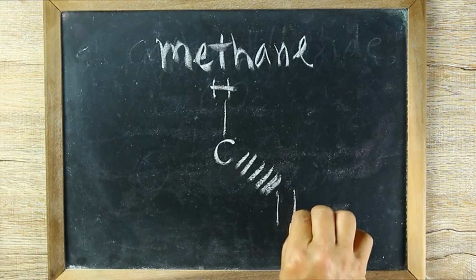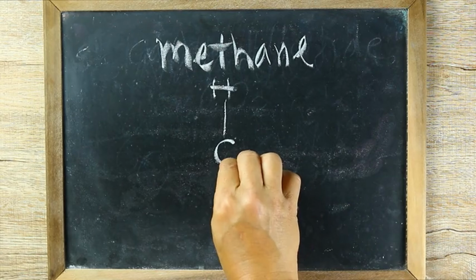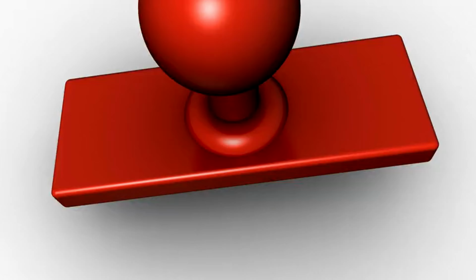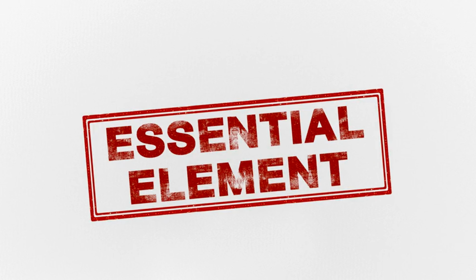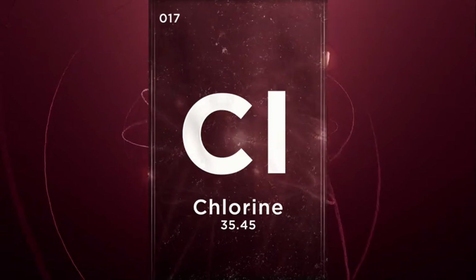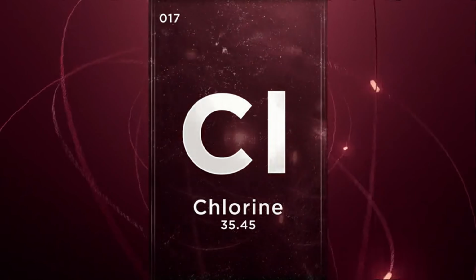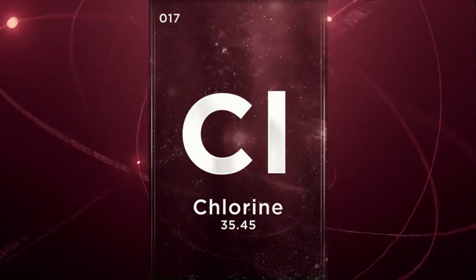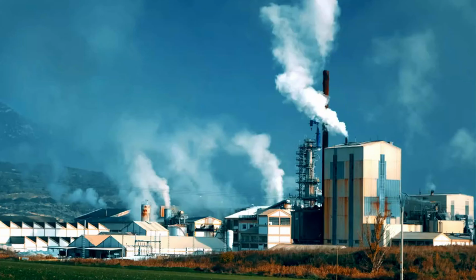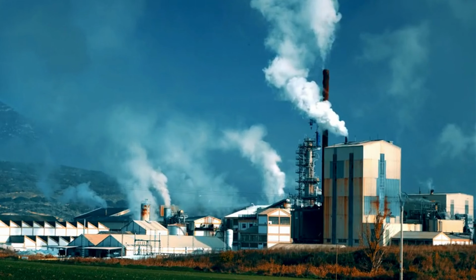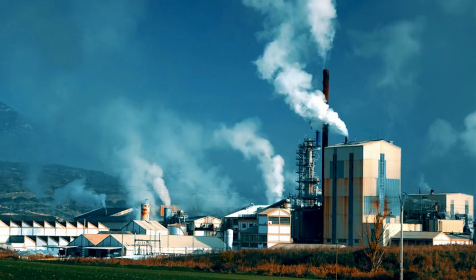Bleaching methods. Elemental chlorine bleaching, the old method, highly polluting. Elemental chlorine-free, ECF, bleaching, uses chlorine dioxide. Totally chlorine-free, TCF, bleaching, uses oxygen, ozone, or hydrogen peroxide. Modern mills favor ECF and TCF methods to reduce environmental impact.